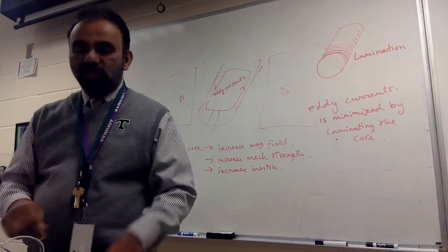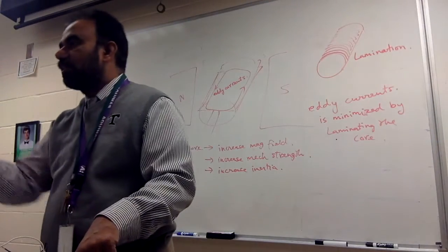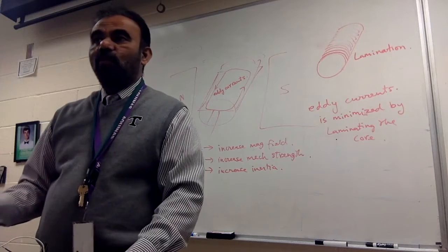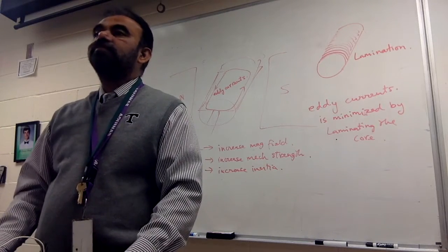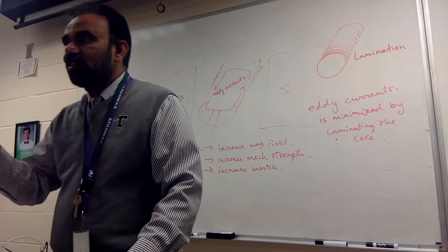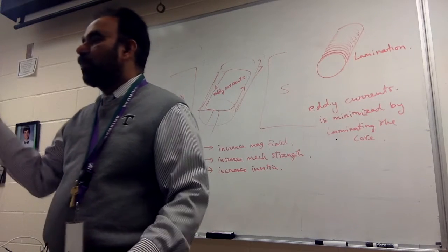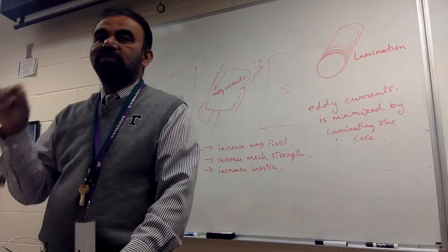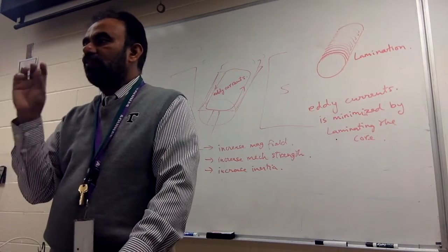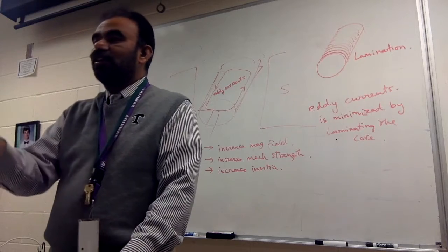It is right to the same. So you connect the thing and immediately look at the meter. The meter is already stopped there at 1 ampere. How did it stop there? What suppressed the oscillation? Eddy currents. And you need eddy currents there to suppress the oscillation. That's why moving coil meters and all those meters use a solid core. And when they use a solid core, we are using eddy currents to stop it.